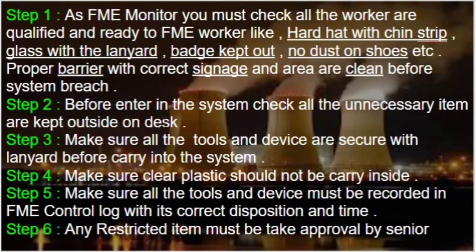The second step is, before entering the system, check that all unnecessary items are kept outside on the desk. That's very important and easy to understand. Make sure all the tools and devices are secured with the lanyard before carrying them into the system. It means all the devices and tools should be secured with a lanyard to protect the system from the introduction of foreign material.